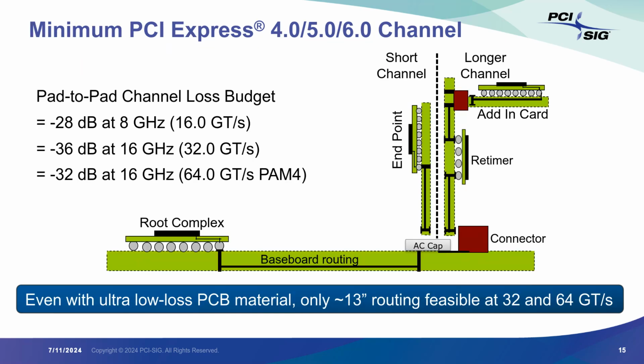In the next two slides, I'm going to briefly cover what we sometimes call the minimum PCI Express channel, because when we develop the base specification, in the beginning you basically have everything open. How do you define the silicon specification, the reference clock specification? How do you define the channel specification?